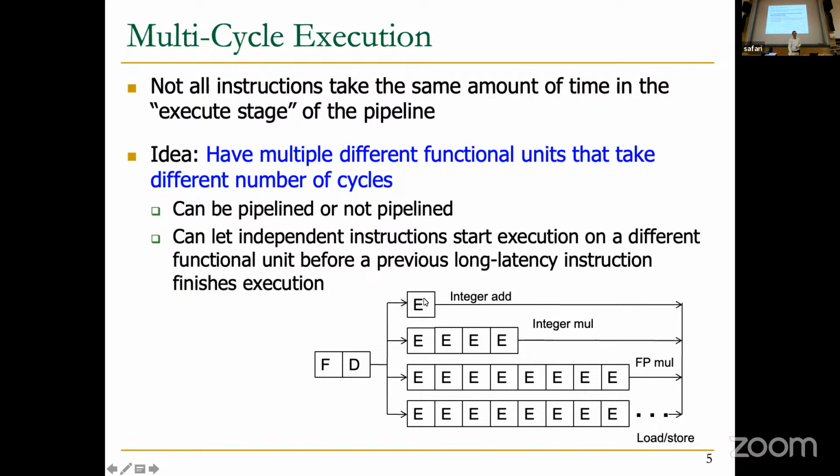But then this add instruction finishes quickly, whereas the multiply is still continuing. Now we have a problem, right? Multiply takes 4 cycles, it's older. Add instruction takes 1 cycle, it's younger. What do? If the add instruction finishes, do you write its result to the register file?